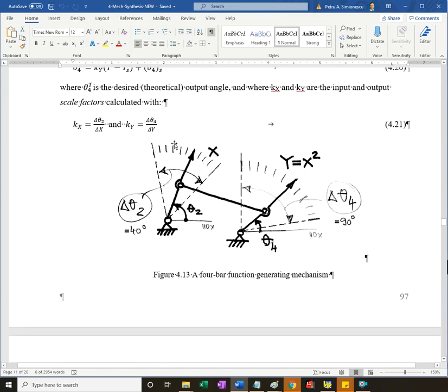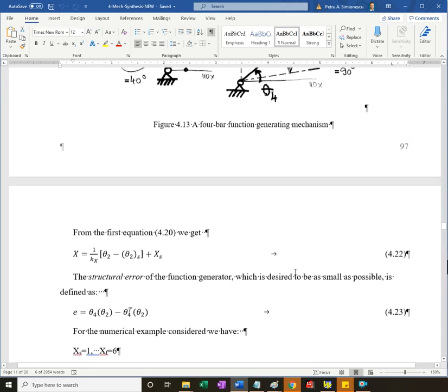You want to have linear scales. That's essential because we can better interpolate on linear scales, versus you could just take any 4-bar, any calibration, but it will have divisions that are spaced unevenly both for the input and output. So yeah, we want to have linear scales for both x and y, the function.